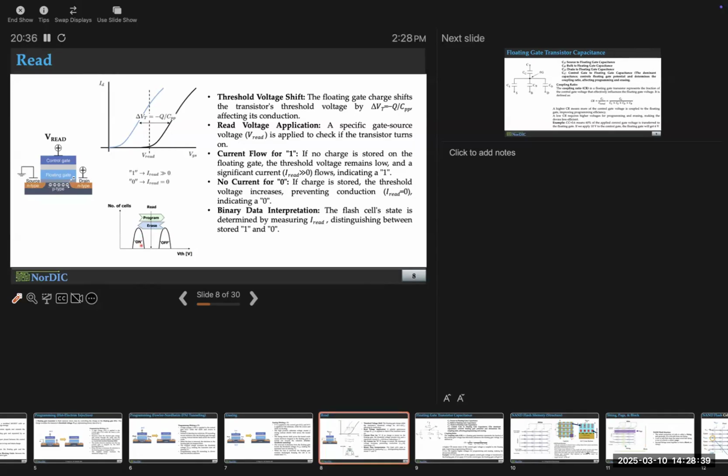Remember, in electronics, there is never a level. There is always a range. Unless you're dealing with something super fancy, like a topological insulator. Look them up. They have absolutely zero variation because of quantum mechanics. Anyways, conventional semiconductors will always have variation. No level will be absolute. There will be a range. So you have a range of threshold voltage when you don't have a trap charge. All you have to do is find a middle ground as a reference. That's all. That's more realistic.